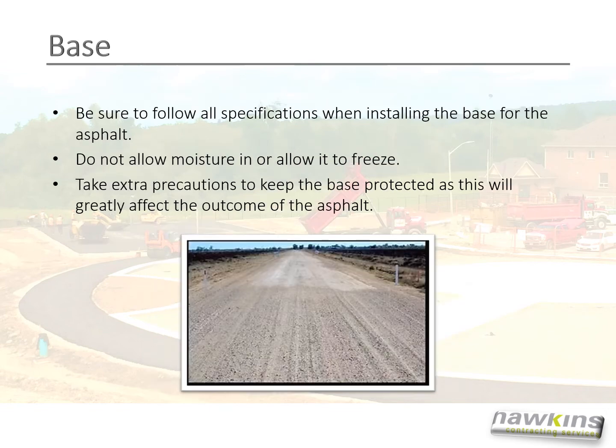This work begins with the base. Be sure to follow all specifications when installing the base for the asphalt. Do not allow moisture in or allow it to freeze. And take extra precautions to keep the base protected, as this will greatly affect the outcome of the asphalt.